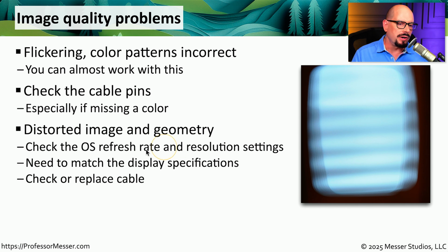You might also want to check your operating system and see what the geometry settings are for this particular monitor and see if there might be any settings for resolution that might be more compatible with the display. A good rule of thumb is to set your computer to match the native display of the monitor to get the best possible screen. So you might want to change the operating system at least temporarily to see if making those changes have any effect on the quality of the screen. And the issue may be related to the cable, so replacing the cable might be an easy check to see if that resolves this particular issue.